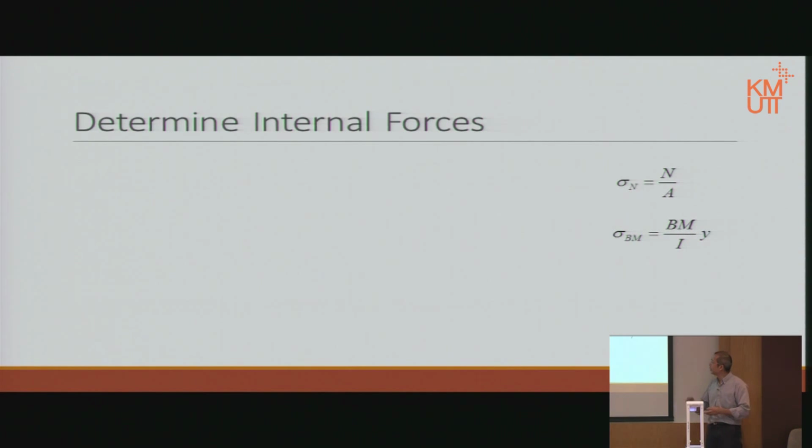We are calculating the combined effect of the stress. Of course, this is axial stress caused by axial force and stress caused by bending moment. Therefore, the first task we should do is find out the axial force, find out the bending moment, then of course the area and the second moment of area.